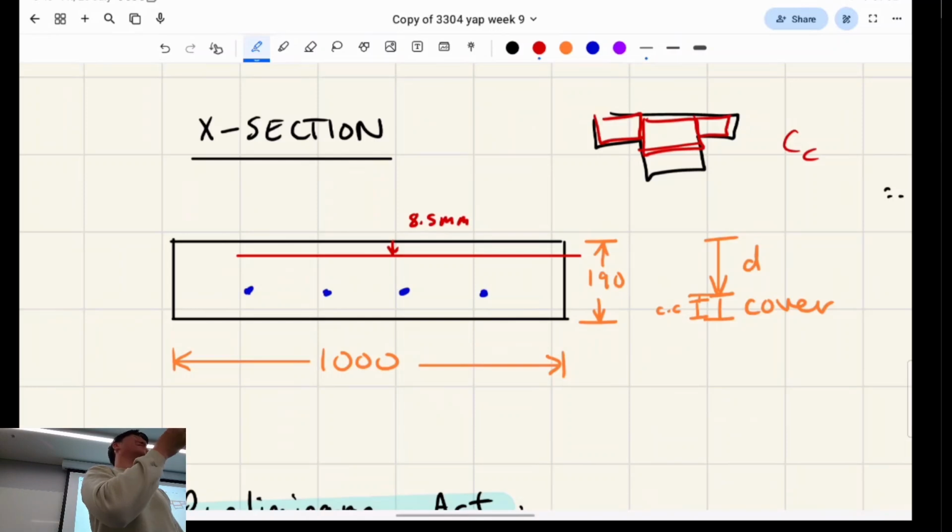But usually in real life, it's not because it's harder to calculate. There are ways to calculate it, it's just a little bit more inconvenient. But they add it because it's also safer. The higher the neutral axis is, the more ductile your section is. So do you reckon in the exams we could need to add compressive reinforcement as well?